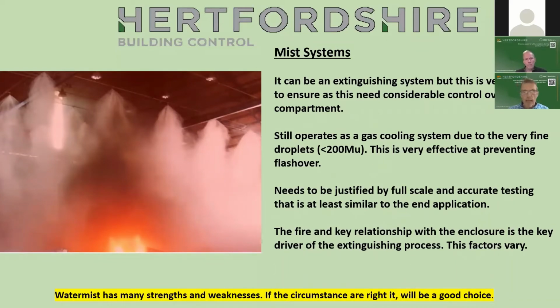Like I've already said, it can be an extinguishing system, but it's very difficult to control over the compartment if it is an extinguishing system. Like I said, it needs an awful lot of research and testing. It still operates as a gas cooling system due to the fine droplets, and this is really effective at preventing flashover. They need to be justified by full-scale and accurate testing that is at least similar to the end application. The fire's relationship with the enclosure is key to the extinguishing process, and the factors vary. Like I said, it's probably the only system where the fire actually drives the extinguishing or the suppression process.